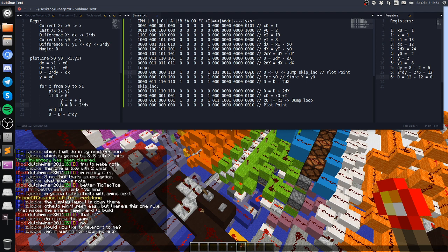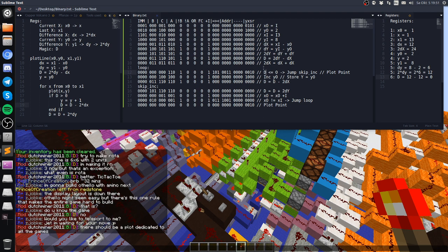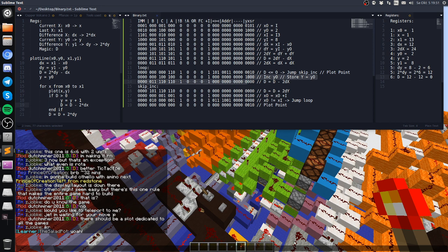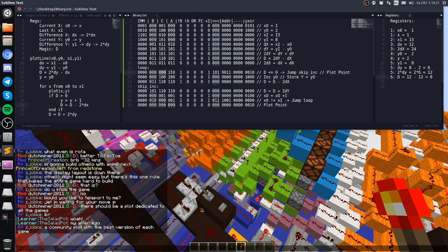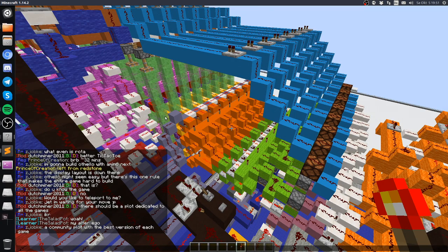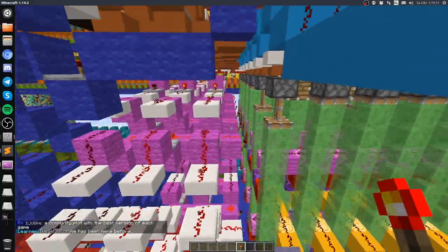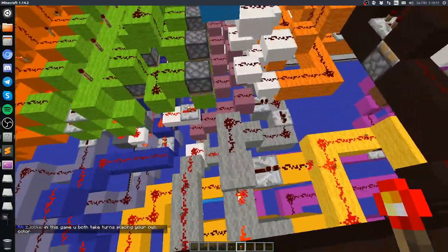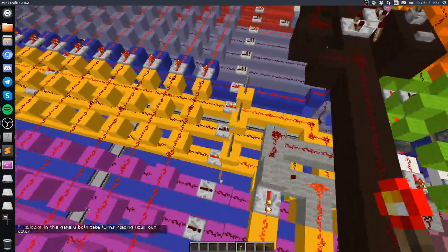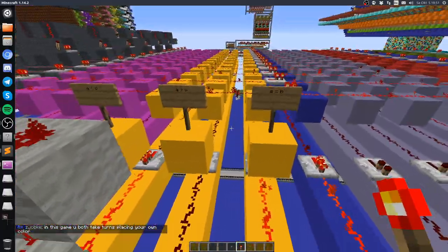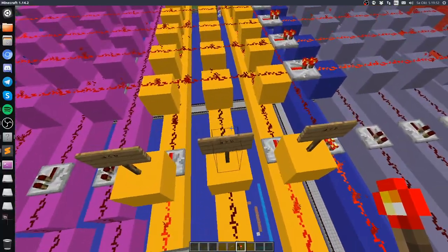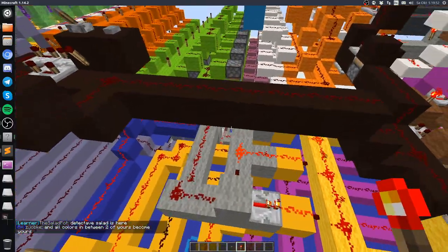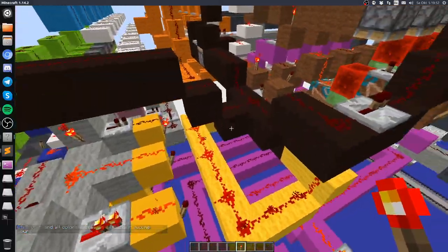So something is obviously wrong with this one. I'm unsure, because it's like never going in here. It's doing subtraction. I can tell these 2 bits are set. It saves to 0, and it loads D into A. So that's D at 6, and that one below is 0, and it saves to 0. So that's all perfectly fine. The point is, which condition does it have? It has the conditions equal or A smaller. It's totally fine actually, because currently it says it's equal. 0 is equal 0, yes. So it will jump.